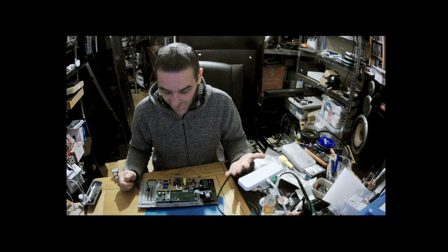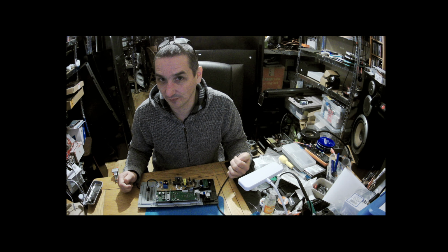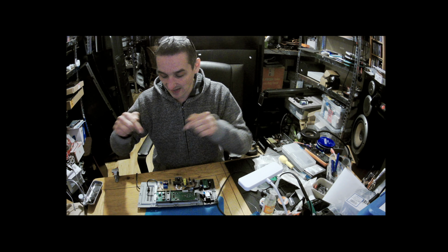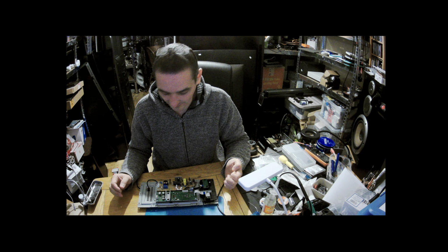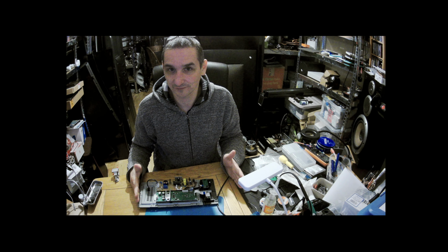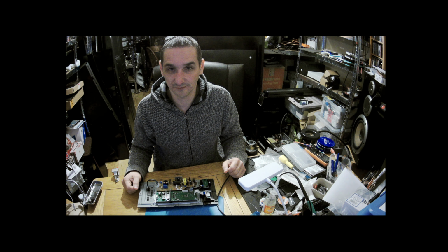Now, what else can be done if that chip is programmable? Okay, that depends how this IC is burned. Because if the IC is burned in a way that you can just supply standby voltage and this will suddenly wake up, then that's fine. But we don't know what is faulty in the IC, so it's a guessing area as well. Sometimes I like to just voltage inject and check. Sometimes they are waking up, and sometimes I'm asking the customer, do you want a full fix, replace the whole board, or do you want to make a Frankenstein?